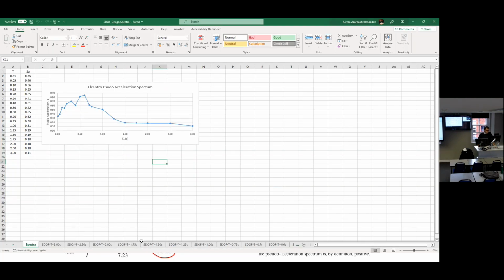Is it because although I increases, I is bigger, but the mass as well? Mass is constant, but I is increased. Yeah, I is in the denominator, and it really decreases sigma. But really, what has increased sigma is the M, the bending moments. The answer relies on the aesthetic shape of this graph. And the answer is,